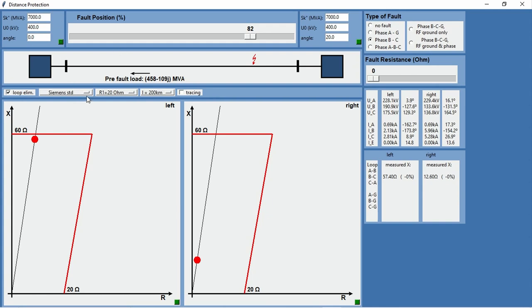Sorry for that, but the algorithm requires that. And I can also show in the simulation what happens. I called it here reactance method. In the manuals you find RMD method. I have now activated this method. And what you see is if I do that, then although we have pre-fault load flow, the movement is horizontal.